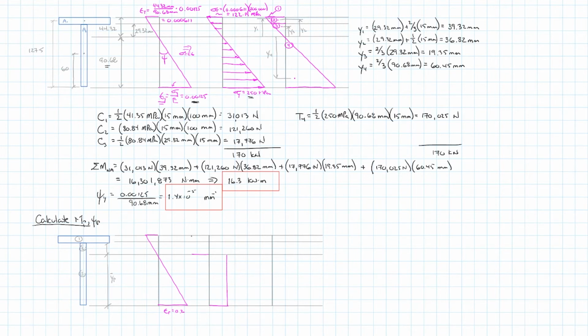In this case, because the entire cross section is plastic, we don't have that Hooke's law relationship between stress and strain anymore. That only occurs during the elastic portion. And so the entire cross section will be at sigma y, and again, we'll draw in our little arrows.